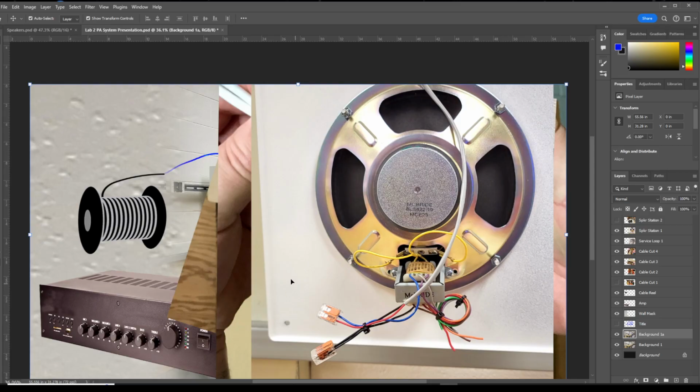So depending on the instructions that the professors might give you, let's say, let's tap all the speakers at 1 watt each. Then you're going to have to find which of the colors applies to 1 watt, and you're going to look at the sticker here. Or we can say, let's tap all speakers to 2 watts each. So you're going to have to find the appropriate color for the 2 watts, and you're going to look at the sticker here. Okay? So just 2 wires are connected from this whole wire bunch.